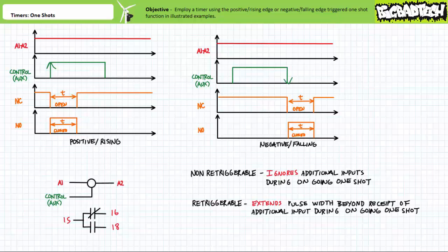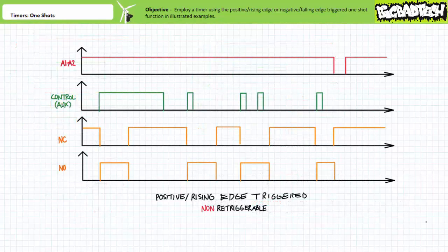Timing diagrams, if you'll recall, show how inputs and outputs relate to each other with respect to time. Consider a non-retriggerable, positive edge triggered one-shot making use of an external power connection without a reset. Let's say the timer is set to 5 seconds. Again, this is an externally powered, non-retriggerable, positive edge triggered one-shot without a reset set for 5 seconds. The only thing that triggers this one-shot is the positive going or rising edge transition of the controlling input. I find that highlighting all the positive edges in the timing diagram helps the analysis procedure. Let's assume each block on this grid is 1 second.